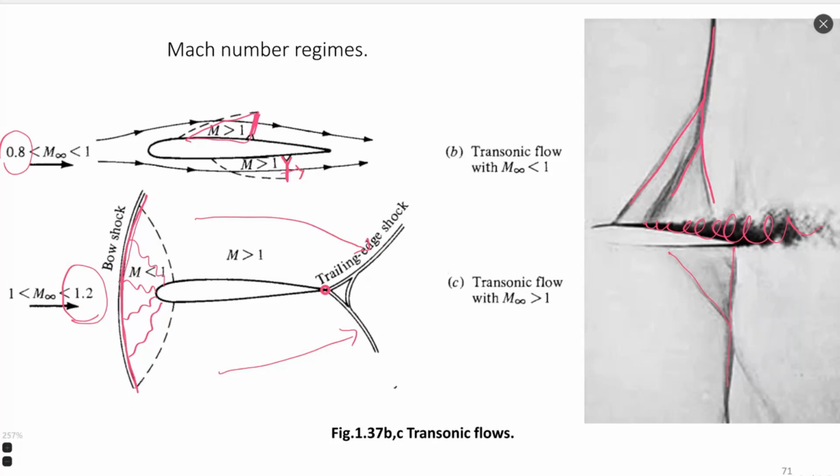which appears because of the existence of the shock wave. The shock wave disturbs a lot. It creates huge gradients of flow parameters, of thermodynamic parameters, and intensifies turbulence in the flow a lot. So it's not possible to have a very nice flow in a transonic regime. I mean, nice from the point of view of lift to drag ratio. It's not good, absolutely. So we would like to avoid such a process, and we cannot use conventional airfoils for such flows because they have very bad lift to drag performance